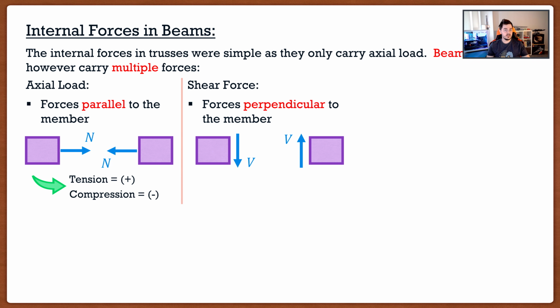One of the things we do as engineers is we want to make sure not only is our building safe, but if somehow it were to fail, we want to make sure that it gives the occupants inside enough time to get out. So for instance, if my roof were to collapse right now, I would design it in such a way that the roof would start to sag a lot. Because then, I would look up and say, oh, the roof's coming down. I better get out. Shear doesn't give that warning time. If my building were to fail in shear, that roof would just break in half. I'd be dead right now. So it's one of those things that shear, it's a killer force, but it's one of the most important ones when we design.